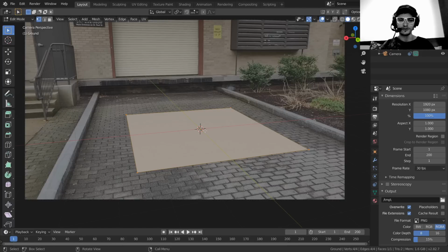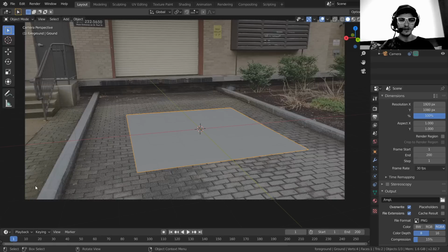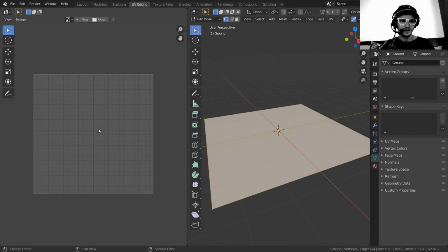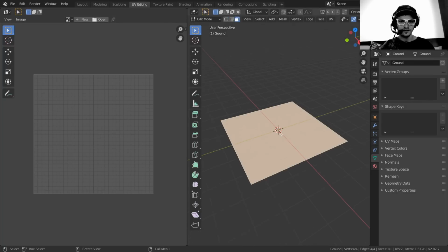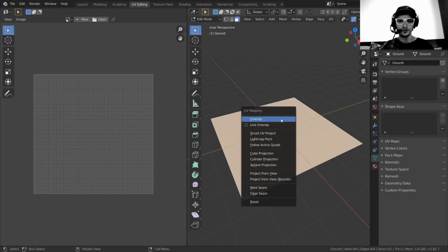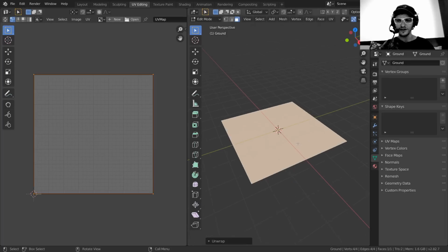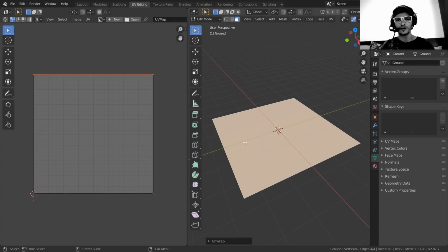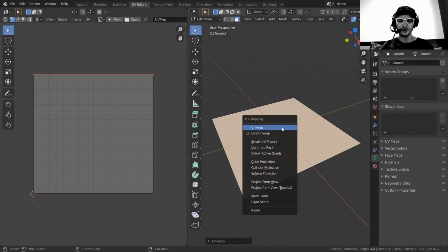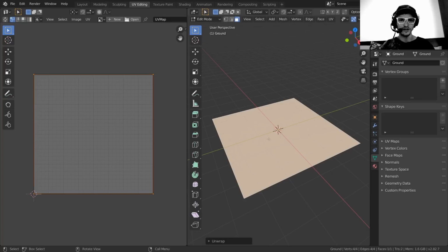And in fact, the method I'm about to do, which I haven't done before, will actually teach you a bit more. So we'll do an infinitely thin thing. So first thing we need to make sure of is that this has a UV map, which it should, but let's check UV editing. Yes, it's a single face, or does it not have, I guess it doesn't. Either way, select your face, U, unwrap, now it's unwrapped. I guess when you hit setup tracking scene, the plane that it adds by default doesn't have a UV map, but now it does. So again, I just hit U, unwrap, now it has a very, very basic unwrap.